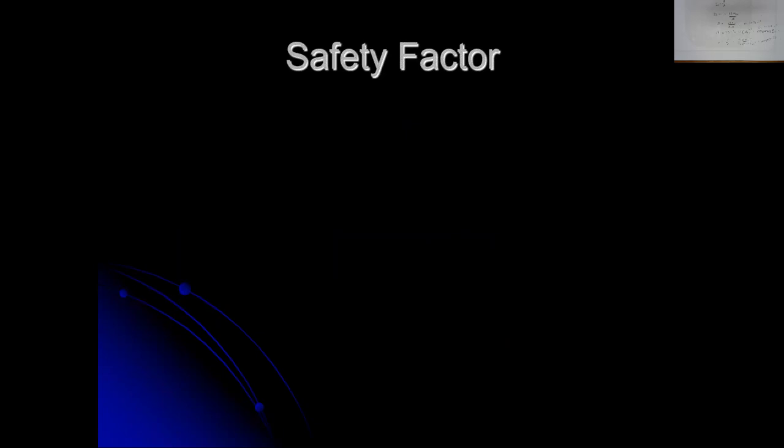So we've got the basic tools. We know what our stress limits are when we're in tension: we've got our yield stress as our limit. When we are shearing, our ultimate shear strength is our limit. We don't worry too much about compression because compression doesn't really have an ultimate strength or even a yield strength. Things don't yield in compression. Instead, they fail by buckling, and buckling is beyond the scope of our class. So we're only going to worry about things in tension or in shear.